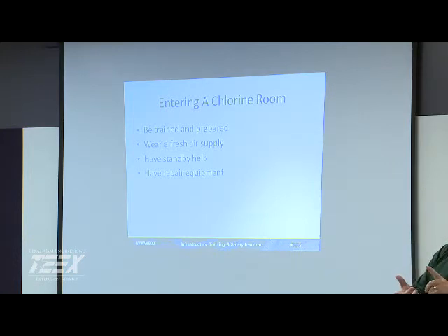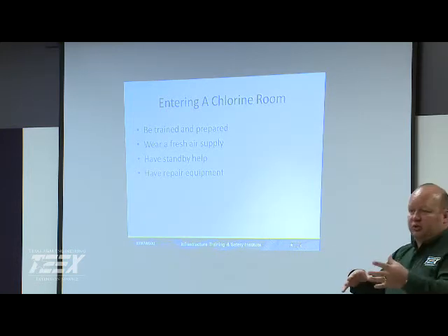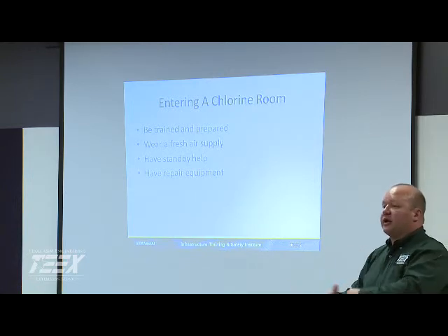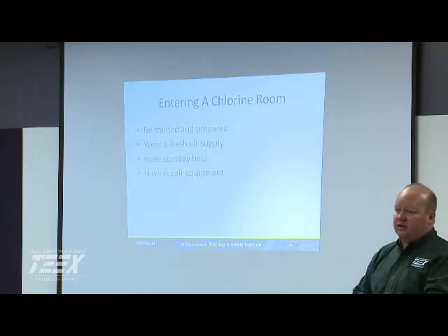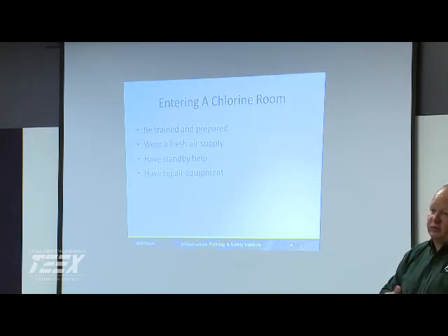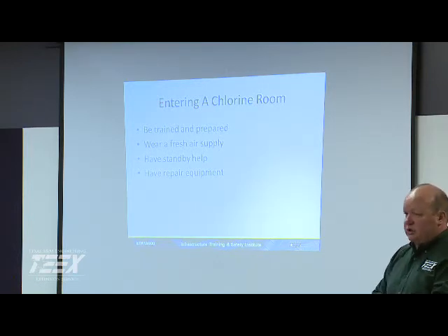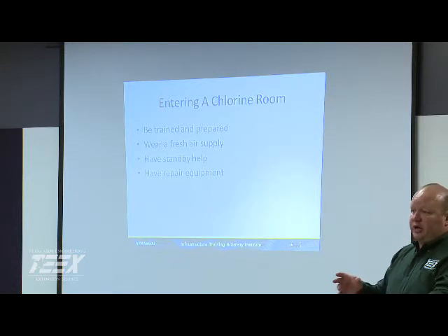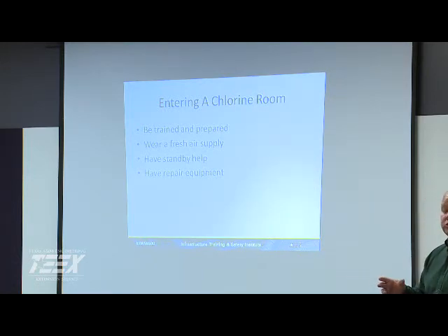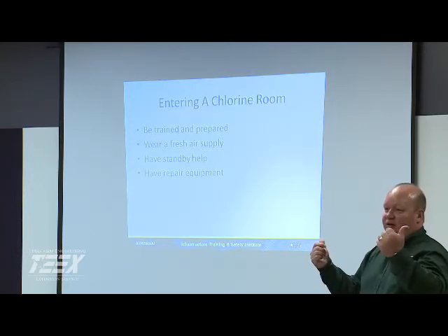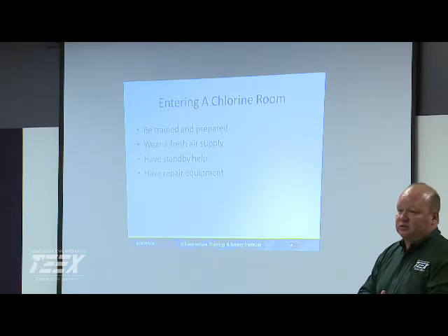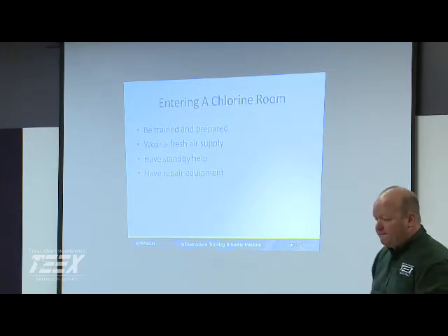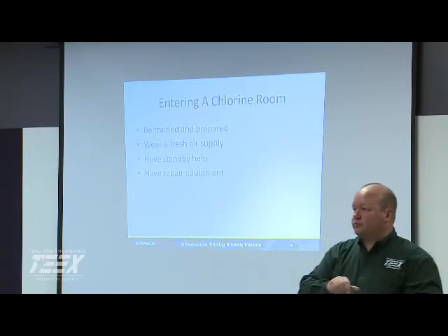Go through some training, and then once you figure out how to use the different components of it, go and practice that. Buying a dummy tank, or a dummy cylinder, is the way to go. That's really the best option for you, because you can actually put it under water pressure and simulate various types of leaks. You know if you get it sealed or not, because if you're still blowing water out, then you'd be blowing gas too. That's something we could probably do whenever we do an inspection.